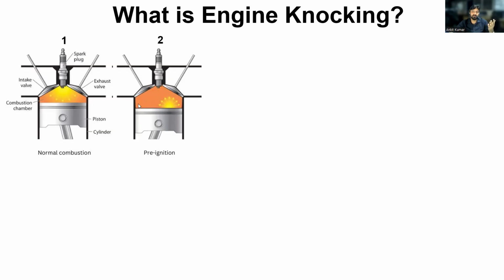So let's say I talk about petrol. Once you compress the petrol-air mixture in this piston, in this engine, what happens? There is a pre-ignition, because petrol is a mixture of various hydrocarbons, and hydrocarbons are connected with weak van der Waals forces or London dispersion forces. And if you compress the piston more, what will happen?